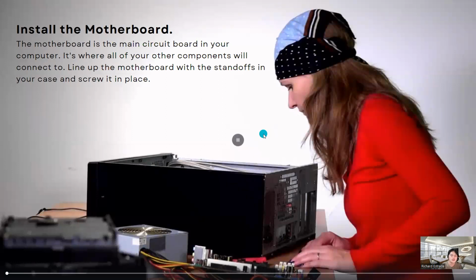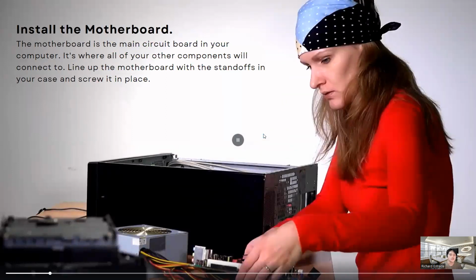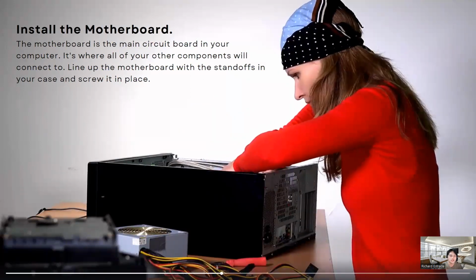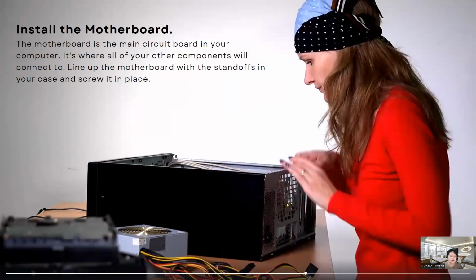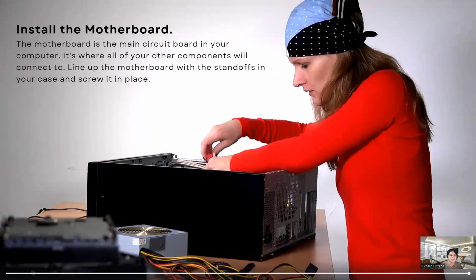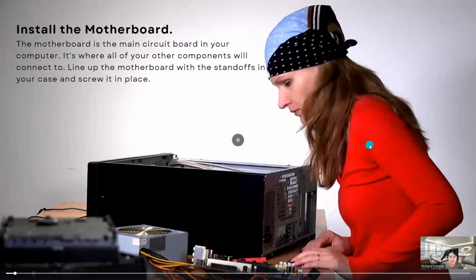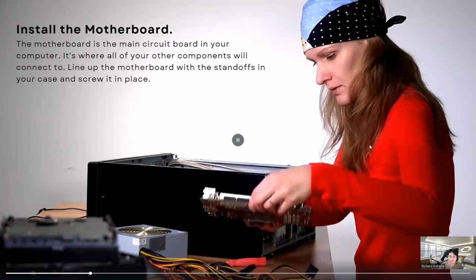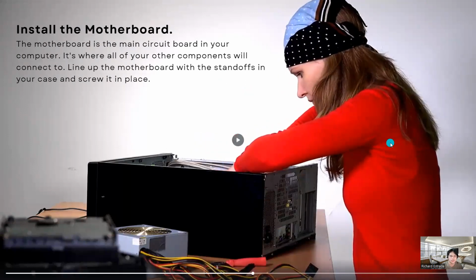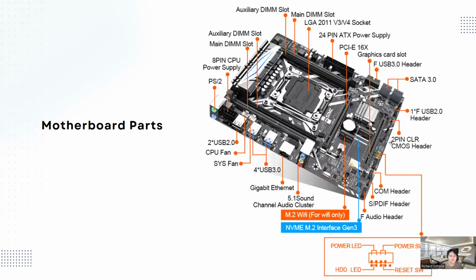Next, what's next? After that, you install the motherboard. The motherboard is the main circuit board in your computer. It's where all your other components will connect to. Then line up the motherboard with the standoffs in your case and screw it in place. So actually, when you start to assemble your computer, and then your motherboard part.